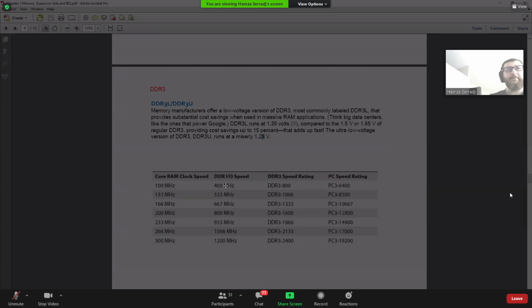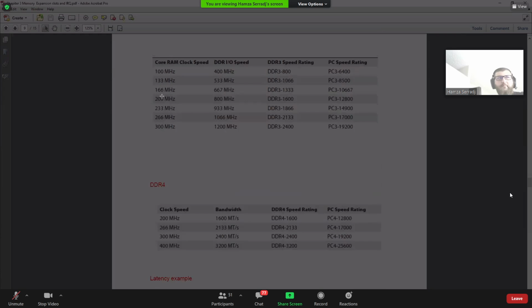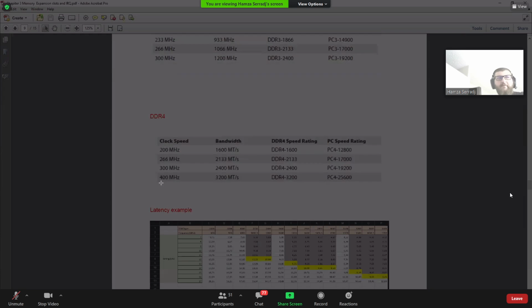We get 2 times the bandwidth, and 2 times that bandwidth from DDR2 to DDR3, so we end up with the 800. So the double of the double, and after the double also on the bandwidth, right? We end up with much higher frequencies, and we can have a higher speed. DDR4, same concept. Those are removed, we start from here, and we have the 400 megahertz, working with the double of the double of the double, logically, right? So we end up with these speeds here.